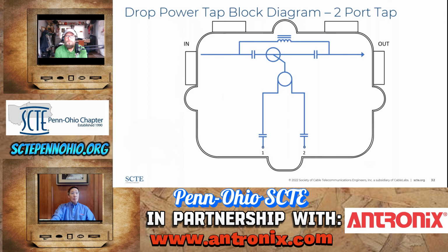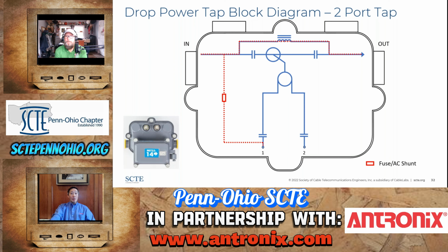This one is a drop power tap, and a drop power tap has one or more F ports that has the capability of providing AC down the drop. And as we mentioned before, this is to power access points, could be Wi-Fi access points, CBRS radios. This is a drop power tap, and this is activated with a fuse as well. It's a little shunt that would put AC and go down one or more of the ports.